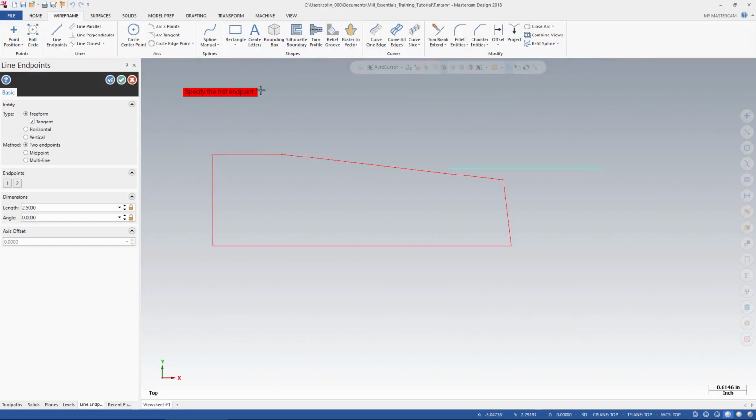Now I want to create another line. I can start it by picking up an existing point on the screen, or I could also type in those coordinates using the fast point mode. Here I'll select it, I'll drag out the line and just click to place it, but now I can go and adjust the dimensions since the line is live.